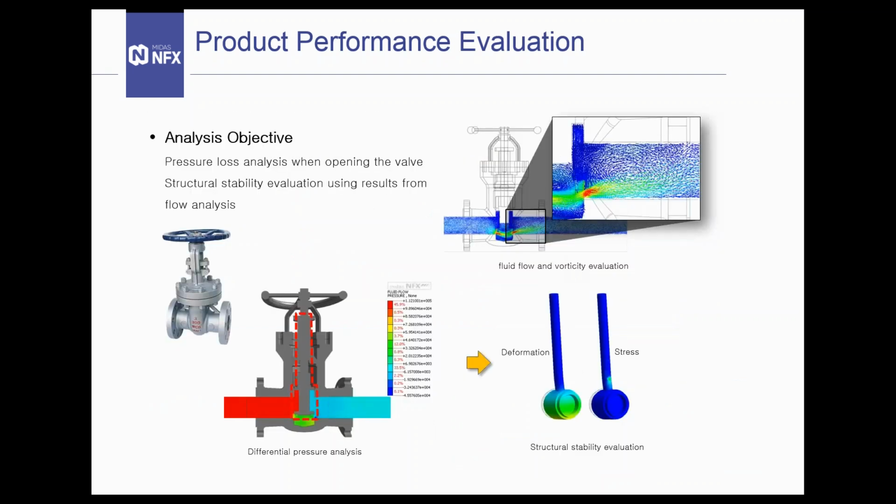Now, coupling of fluid pressure calculation with structural analysis through fluid structure interaction is useful to detect the impact of the inner fluid on the product. As you can see in this example of a valve, you can analyze the flow, and then you'll get deformation and stresses on the structural model, and then you'll know how to improve your design.